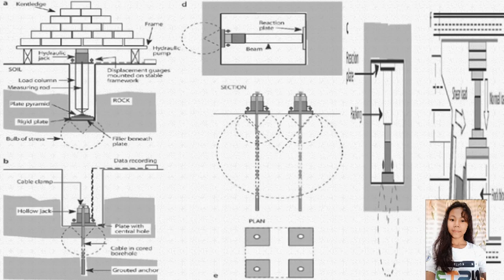In uniformly weathered rock, the objective is to find the depth of the weathered layer which has deformation characteristics adequate enough to fulfill construction criteria. This means multiple plate-bearing tests, which may be achieved if the reaction to plate load is given by a cable anchored at some considerable depth below the shallowest test level.